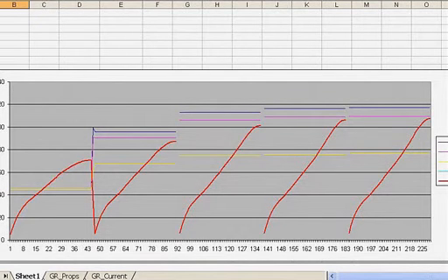So this illustrates effectively how we can solve a difficult question. We've got a transient magnetic problem occurring in microseconds, along with a time constant in the temperature domain of probably 10,000 seconds. It seems to take about 10,000 seconds to have this problem converge to steady state. So on the surface, you'd say that's not possible. You have to couple times in the same time domain. But by using the ActiveField, we can split that.